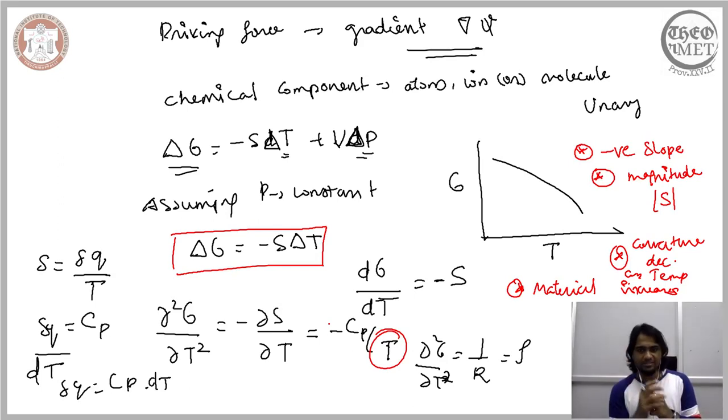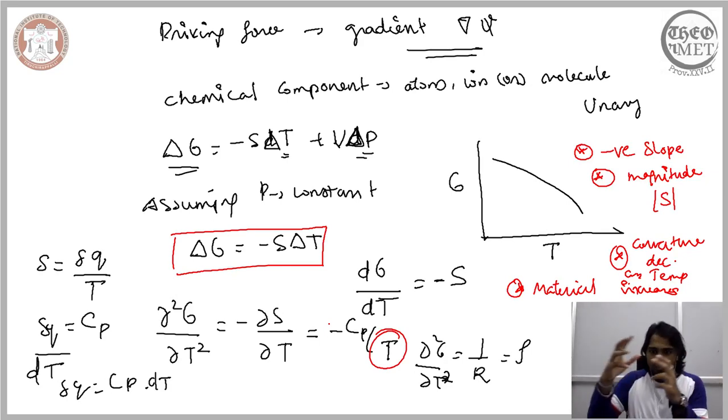So what have we considered? What are the characteristic features of the Gibbs free energy and temperature curve? Apart from the negative slope that is indicative of the entropy, and the nature of the slope that can be understood by considering its curvature, the other takeaway point from this schematic representation of the change in the Gibbs free energy with respect to temperature for a single component system is when there is a change in the heat capacity.